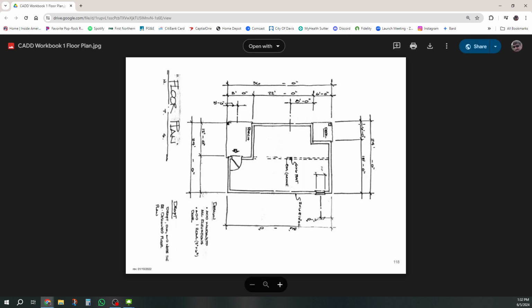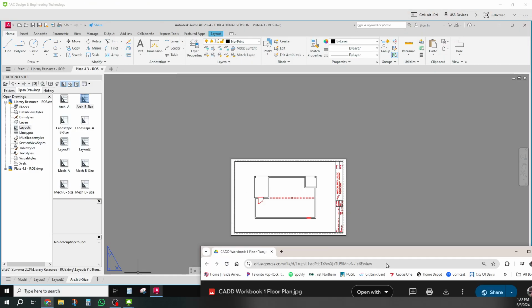So it should kind of look like this. Here's this part, and there's the overall. Here's this part, and this part, the overall. This part, the overall. And then these are just locating off of an external wall to the midpoint. Also, when we do a real dimensioning job, you read everything from the right side to the left side, or from the bottom to the top. So this drawing should really be rotated and it would look right. Okay, but we're going to have to work on that ourselves.